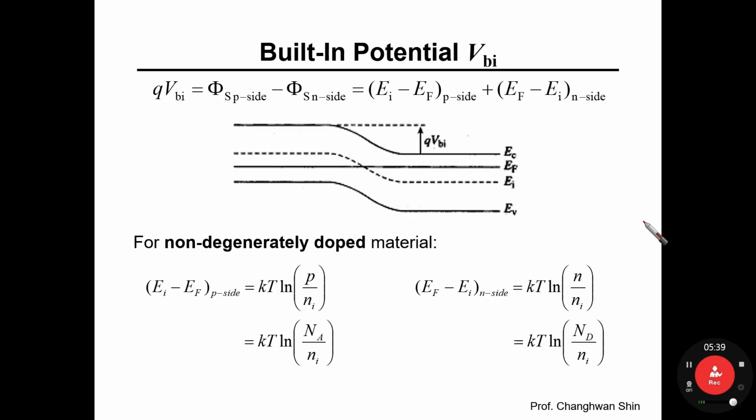So in that sense, PN junction theory is the most basic building block in understanding the parasitic capacitive components in the MOSFET in integrated circuits. I guess this class will provide you with some more basics and fundamentals of the physical origin of capacitive components in the MOSFET. How come the capacitive components are always hanging together with resistance components? That must originate from the depletion region. So how come the depletion region would be formed between the p side and n side?